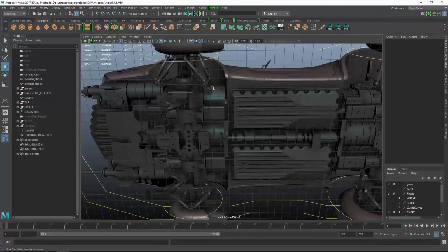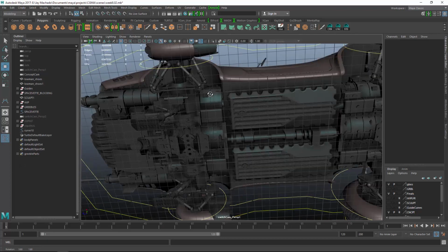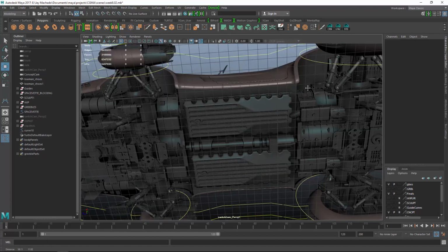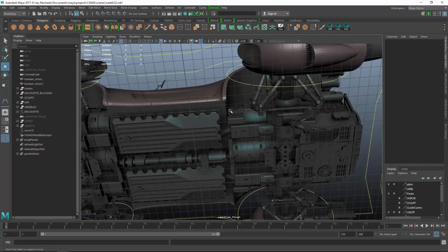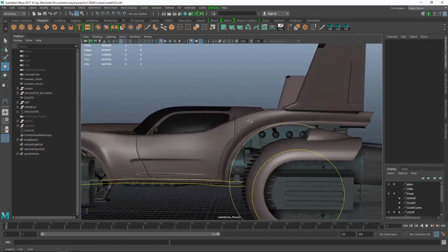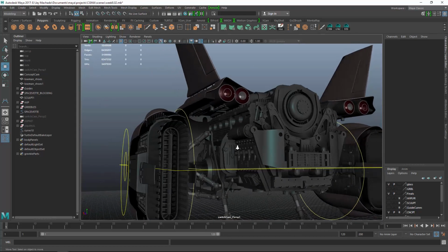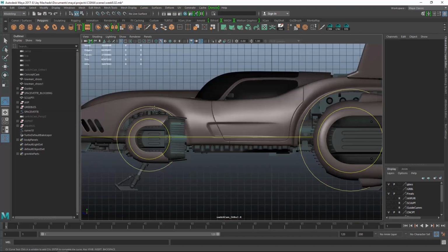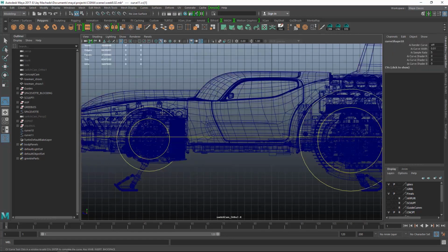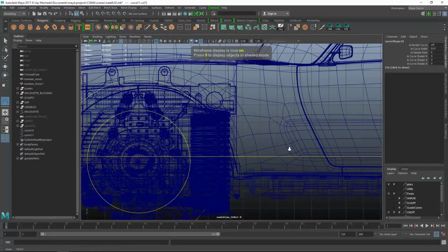I think I want to do a muffler type pipe here that goes from this area here and around the bottom here next to the door, and then maybe across the top end. Maybe it could hook up to these pipes in here. So let me get my CV curve tool, and I'm gonna overshoot that area a bit, just so we have some control vertices to play with.